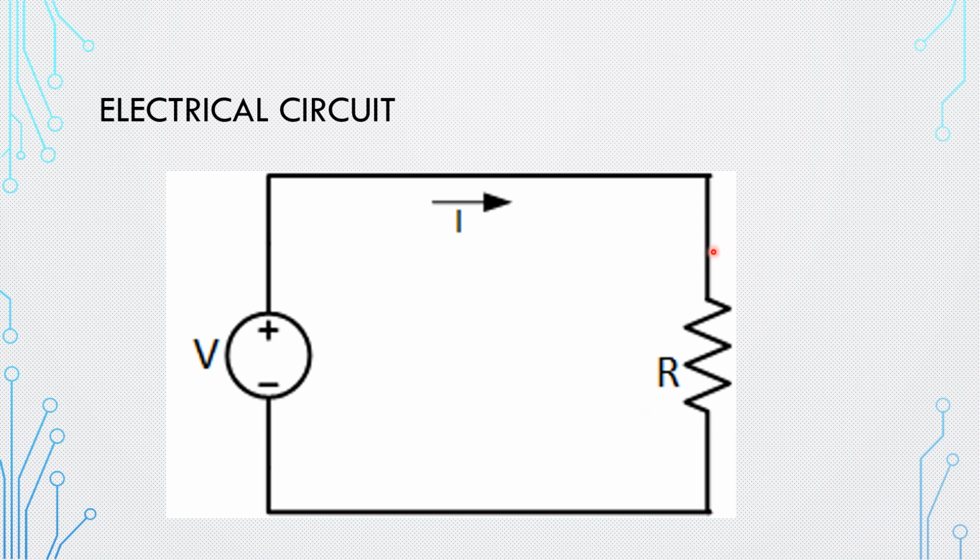So we have some formula that relates these three elements together. We'll talk about it later, but from this experiment, to create a circuit we have to have these three elements connected together. We don't have any circuit that is missing one of these three. If I'm having current, I'm gonna have voltage, and most likely in our lab, and for most of the course, we're gonna measure the current and voltage through the resistor.